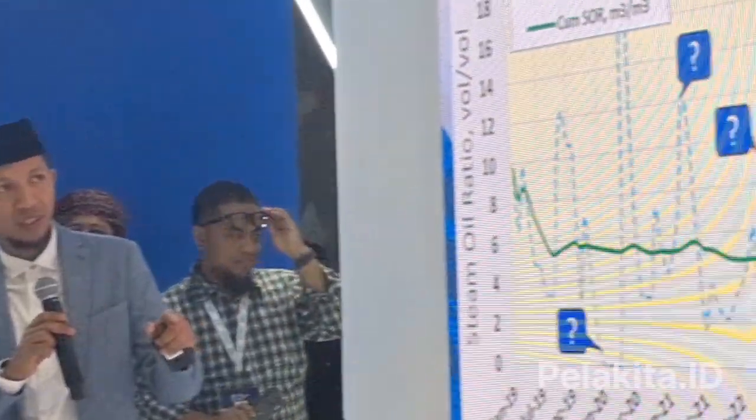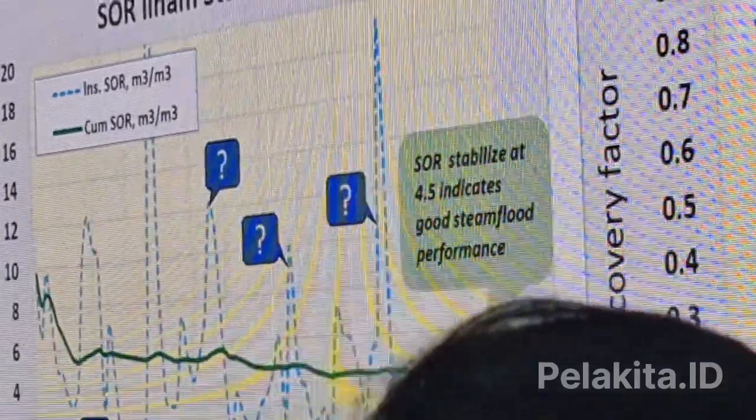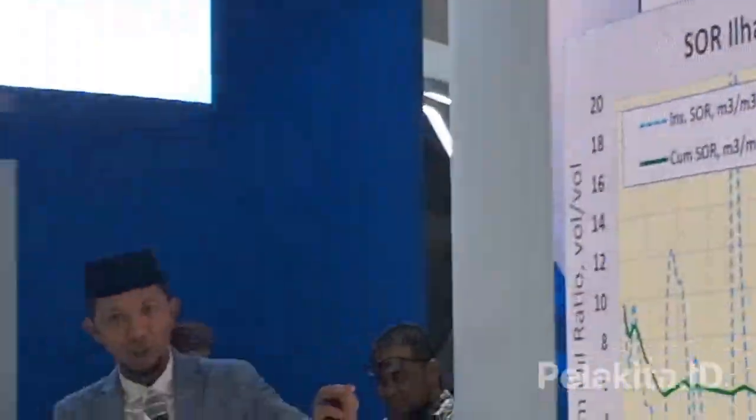This is very important. The changing of your endpoints, like critical saturation, KROW, and residual oil, relates to the changing of temperature, because this is what happens in the reservoir. So that's the main parameter that we adjusted to get this good history matching here.